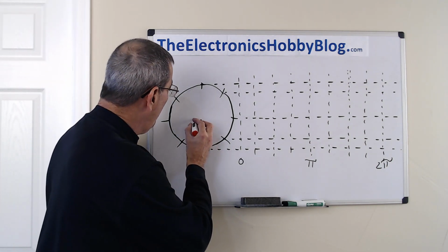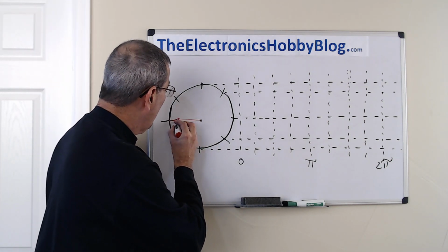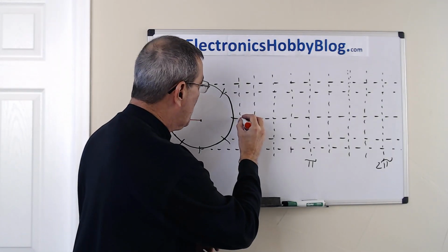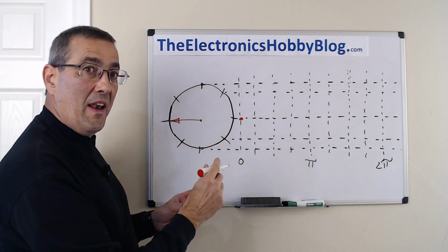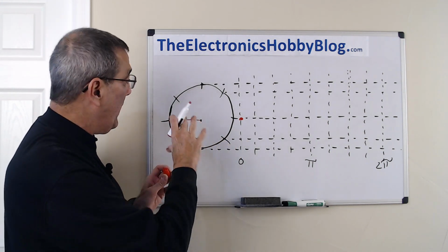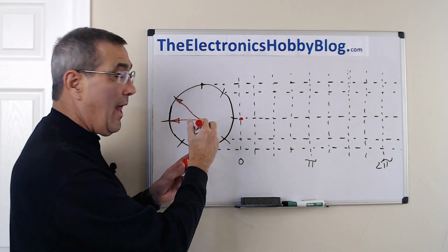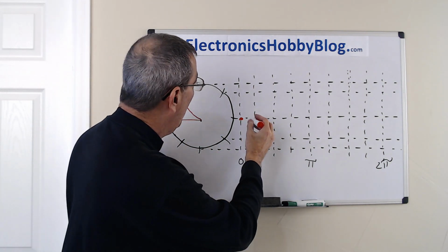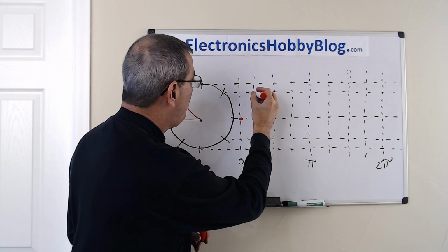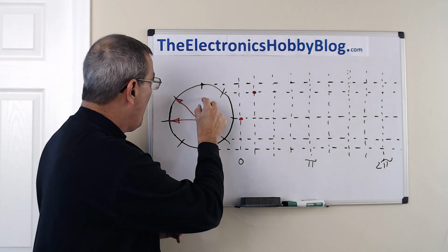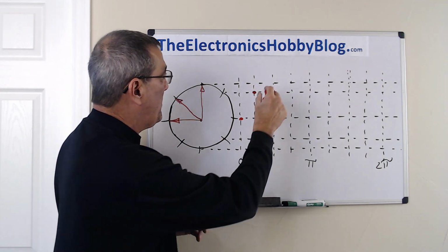Well, let's assume, we'll use a phasor here to point, and let's assume we start here. And that's going to be the start of our waveform. And now, as the windings rotate, as the armature rotates, it reaches this position. And that happens an X time later. And we'll say that's right here. So we'll move there. Okay, then the armature rotates some more and we reach this position.